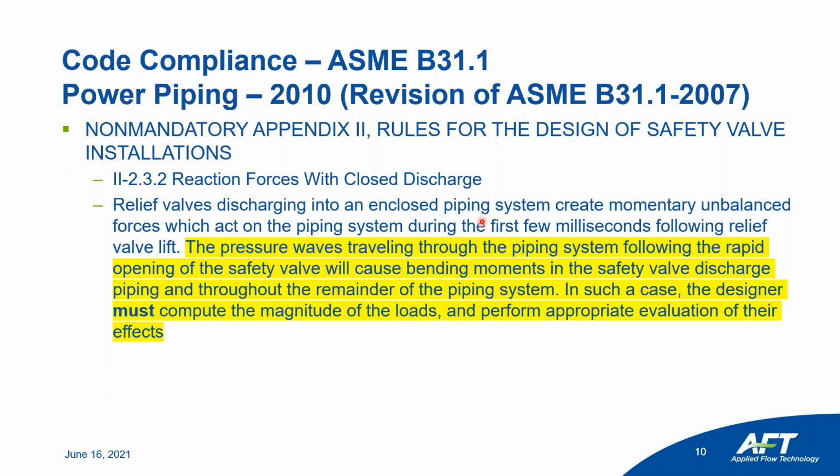Relief valve discharging into an enclosed piping system, and sometimes when it says an enclosed piping system, it refers to a header, creates momentary unbalanced forces which act on a piping system during the first few milliseconds following the valve lift. The pressure waves traveling through the piping system following the rapid opening of a safety valve will cause bending moments in the safety valve discharge piping and throughout the remainder of the piping system. In such case, the designer must, and it's interesting because this is a non-mandatory appendix, but it uses the word must, compute the magnitude of the loads and perform an appropriate evaluation of their effects. As you can see, it just warns you and requests you to do the calculation of the wave traveling when the relief valve opens, but it doesn't give you any guidance on how to calculate dynamic forces.